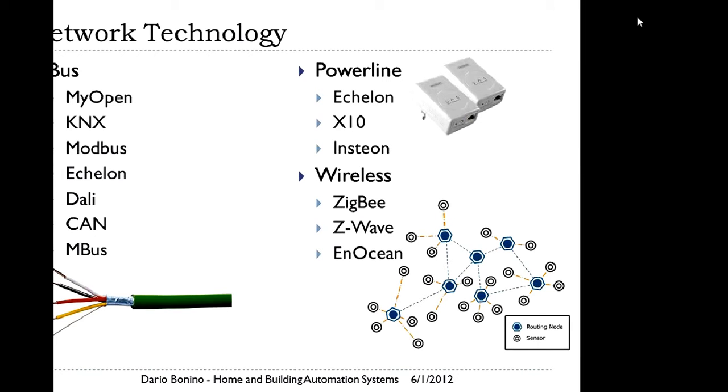And these are also useful for retrofitting, basically, because you can dispose of the devices all over the building or the home without almost any constraint apart from walls. So if you have walls between devices, then the communication range shortens, basically. So if you have 100 meters of maximum communication distance outdoors, inside, that dramatically drops to 10 meters or 7 meters or 15 meters. It depends on the thickness of the wall, on how much metal is inside the wall, and so on.